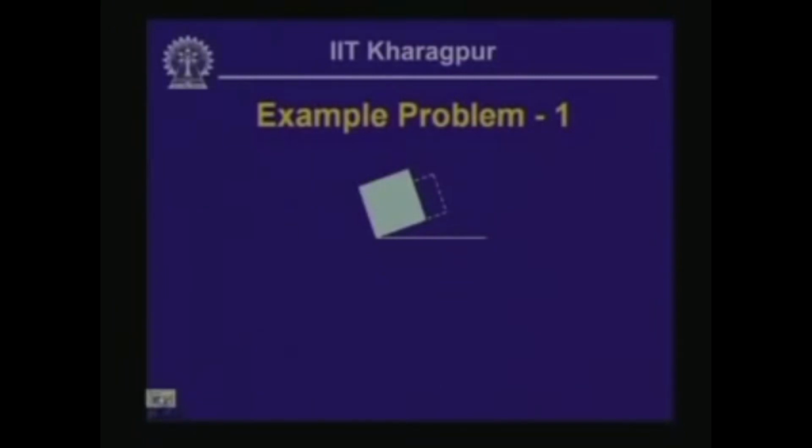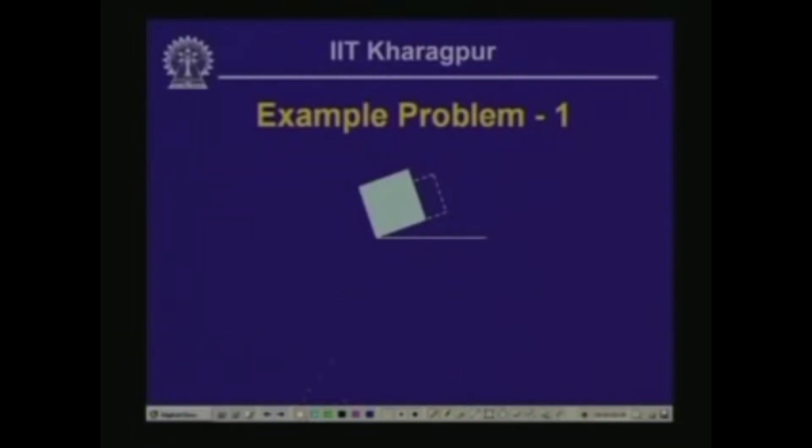Now, this is the orientation or the final form of the reference plane, if this is the x direction and this is the y direction. Now, we have the orientation for the principal plane, which is theta p of 14.3 degrees. So, this is the direction along which the principal strain acts. So, this is epsilon 1 and in this direction we have epsilon 2. Now, epsilon 2 was negative and that is why it is compressed and this is elongated. So, this is the form of the principal strain.